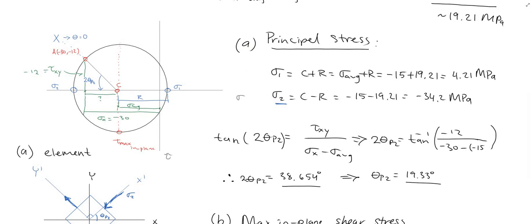But we also need the rotation of this element. So how do we find that? Well, we go back to our reference point, and then we have a look at what is the rotation from the reference to the shear axis. So let's look at the max shear axis down here. So we're just going to draw this out in there. And again, I'm just going to look at this graphically, and what I will see is that, first of all, S2. What we'll find is that we can simply just add the 90 degrees in here to this angle that we found earlier.